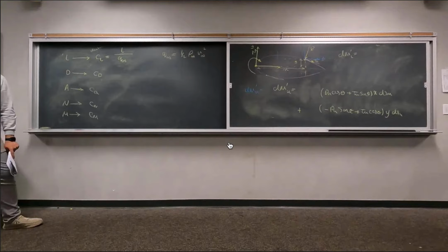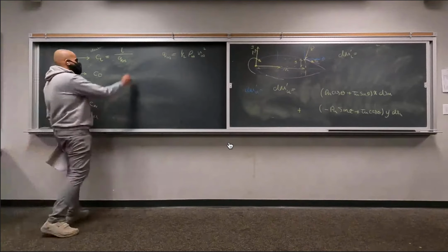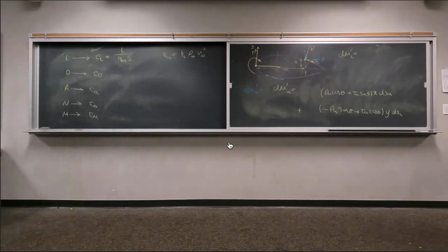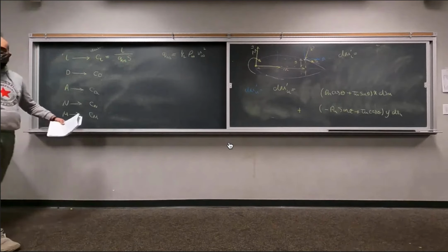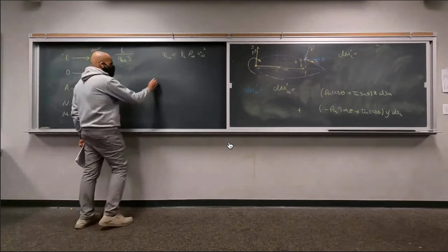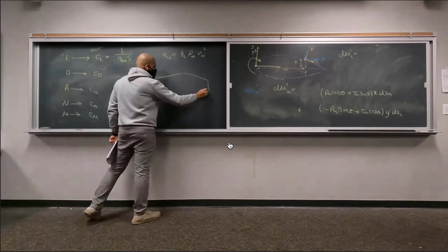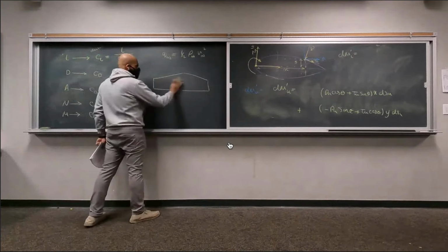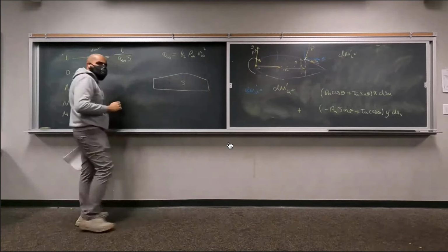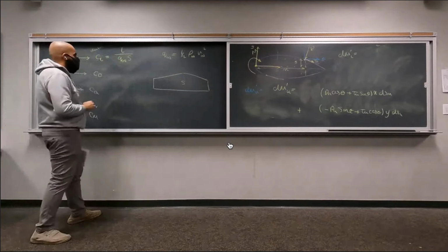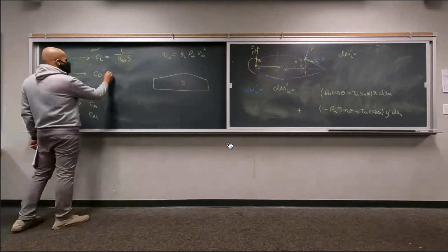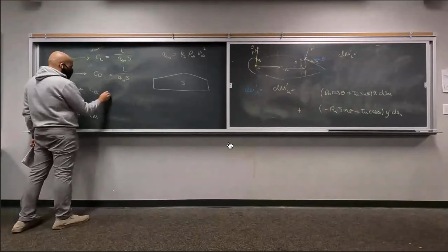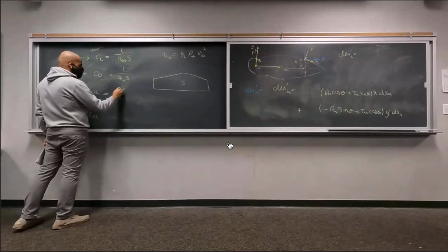It's pressure, right? So newtons per meter square. So we have to multiply it by the area of your object. For a wing, it is going to be your span area. Let's say this is a top view of a wing. The whole area of this wing is called the span area. So S. Lift coefficient, the same thing: L over Q infinity S, and the same thing for the other coefficients.